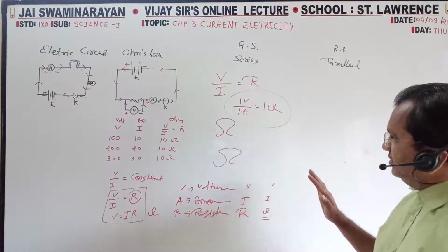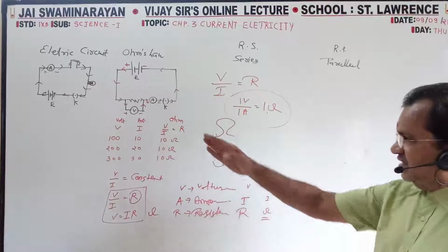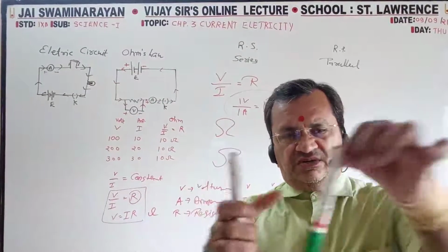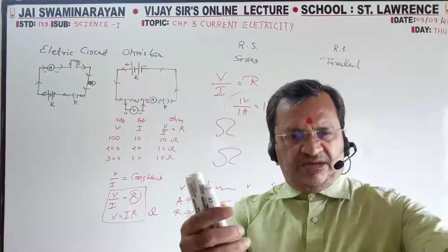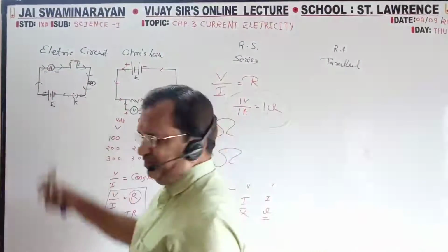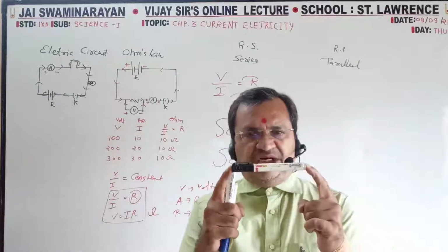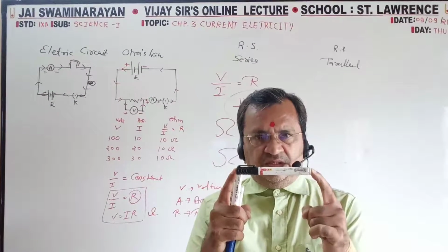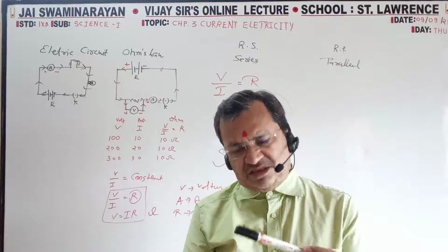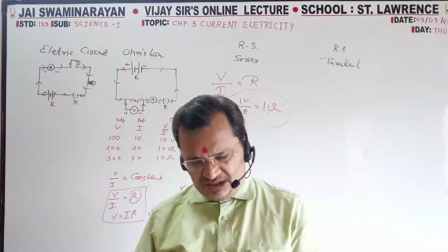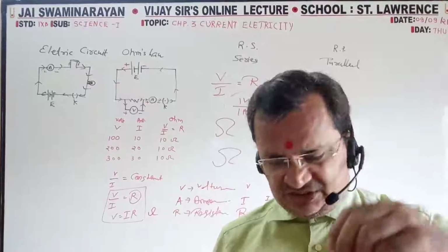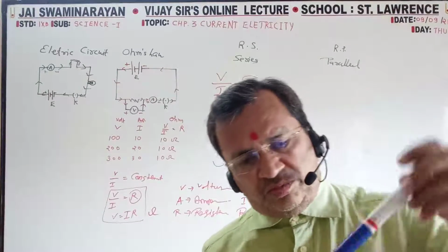So first part done, second part done. This is a small part, this is a circuit. Through this circuit we can identify the different rods, I am taking 3 or 4 of different colors. I have to fill this gap, meaning two terminals will be touched. If the bulb glows, it is conducting. If it is not glowing, non-conducting. Then next, to measure ohm, the resistance.